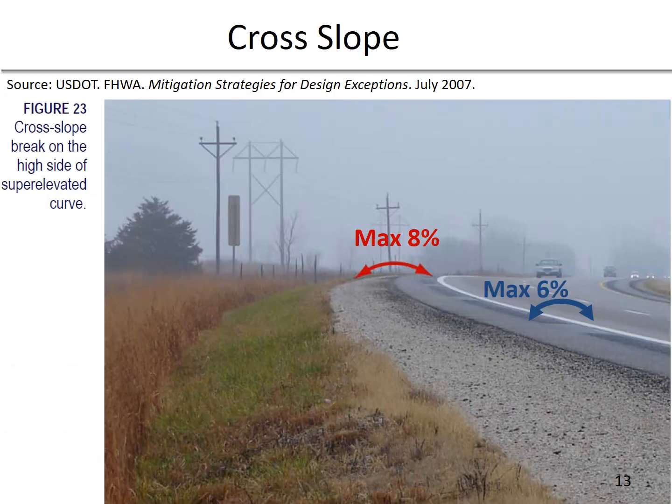Pavement cross slope is an important cross-section design element. The cross slope drains water from the roadway laterally and helps minimize ponding of water on the pavement. This prevents maintenance issues and also minimizes icing from occurring on poorly drained pavement. On roadways with curbed cross sections, the cross slope moves the water to a narrower channel adjacent to the curb, away from the travel lanes where it can be removed.